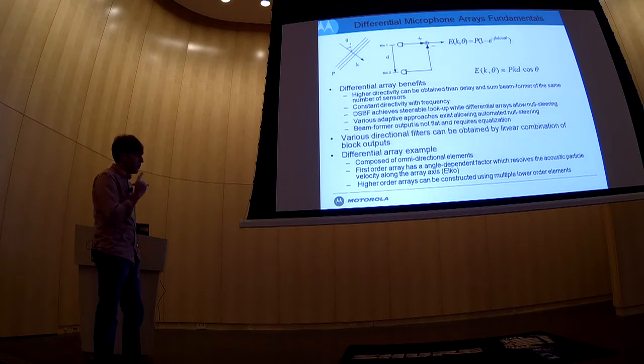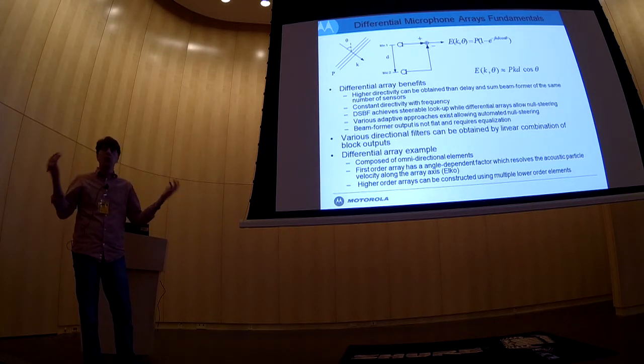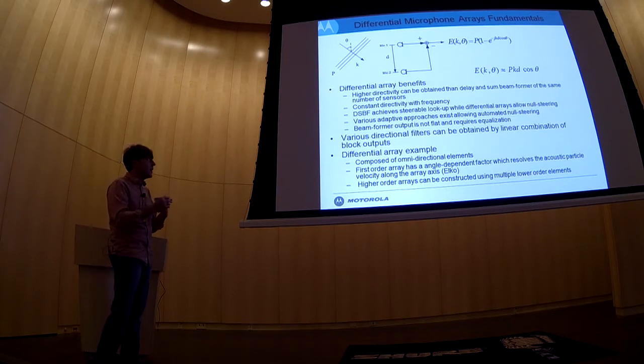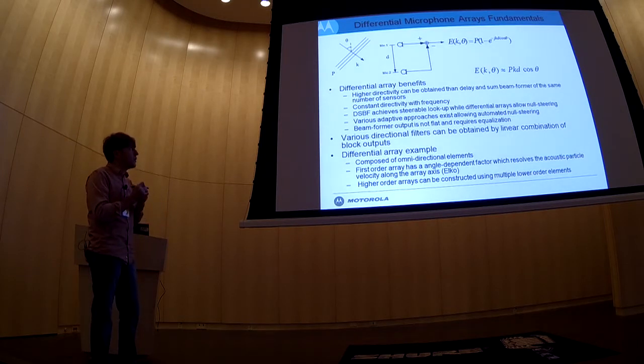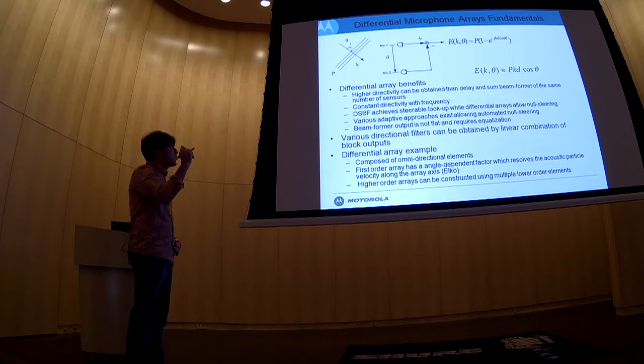How does the differential array work? Well, first of all, there's two microphones. They are located at 2 points in space, so we really are exploiting spatial diversity. And they work to find a directional gradient along that line. The directional gradient of the sound field approaching will be maximum if the source of origin is along the same direction.